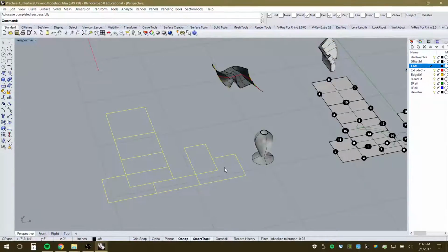Then I can open it up in AutoCAD. Use the laser template file. I would still have to scale it. This would have to be scaled down. This is all full scale, right? When you're drawing in virtual modeling, you want to make sure that you're drawing at 1-to-1 scale. And then you scale that overall object down to whatever scale the model is going to be. So 1/48 for a 1/4 inch and so forth. Scale it down, and then you could adjust the properties and so forth for the laser cutting template file, and then make the cuts, and then basically you'd be able to make the physical box.